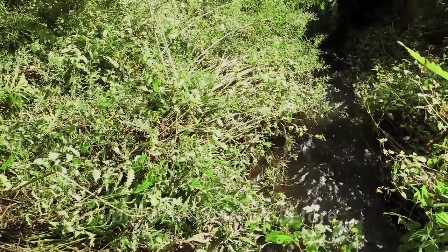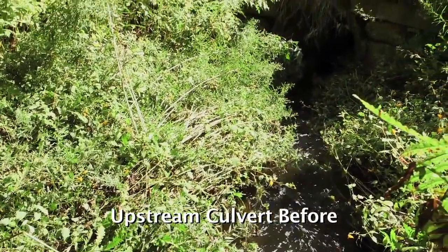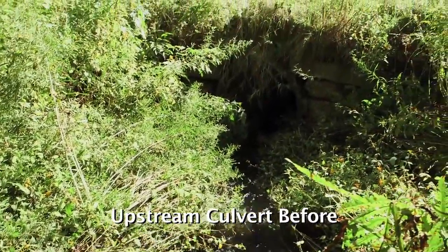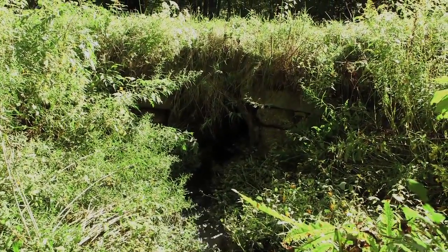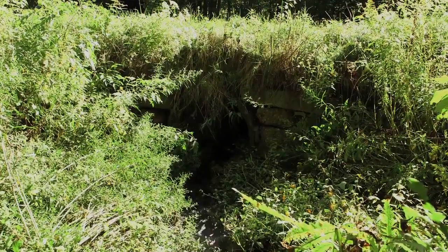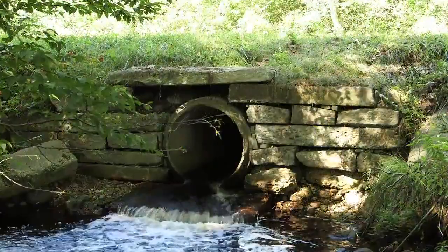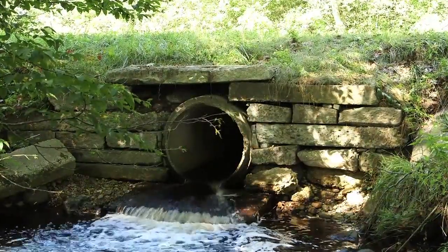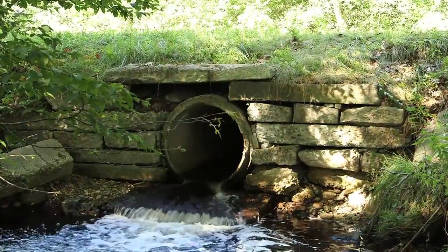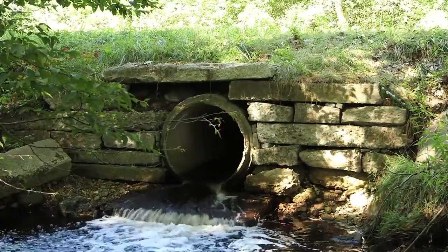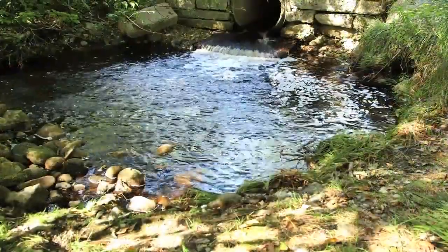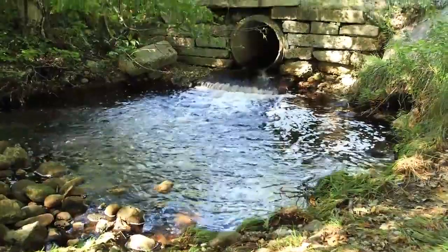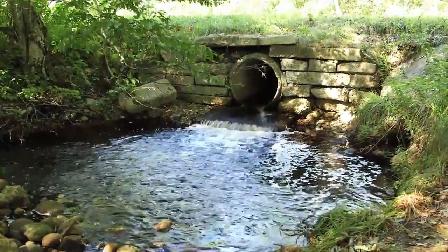Water control. Water control typically consists of diverting all existing stream flow around or through the working area of the construction site, keeping any of the stream flow clean as it passes through the crossing area. For this site, the existing pipe was used to bypass clean water through the construction site instead of pumping the water around the site during construction. This is the downstream end of the old culvert before any work started.